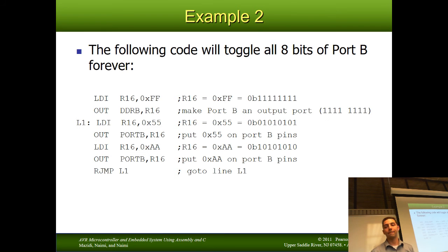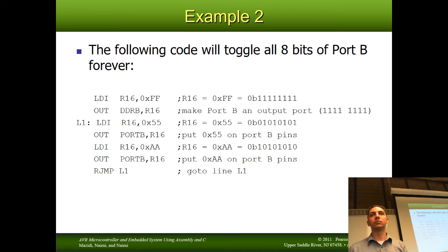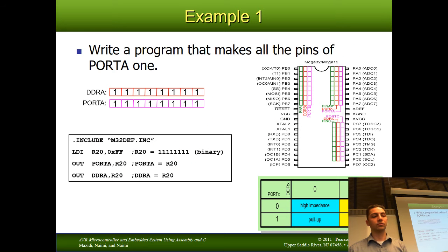Alex. I thought you said you have to set the DDR to 1 before you can set high. I did. But in the previous slide, you did port A to FF and then DDR. Okay. Valid observation. Let's go through what actually happened. So let's assume for a moment, you're right.